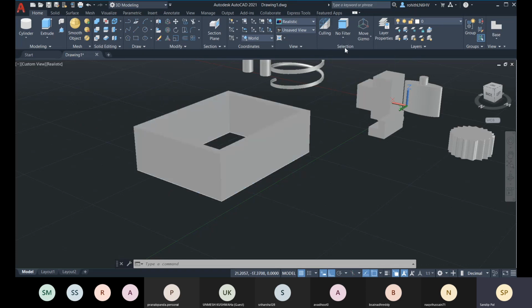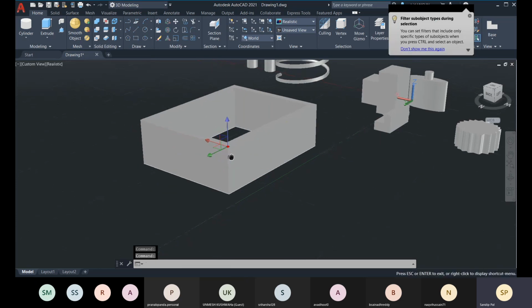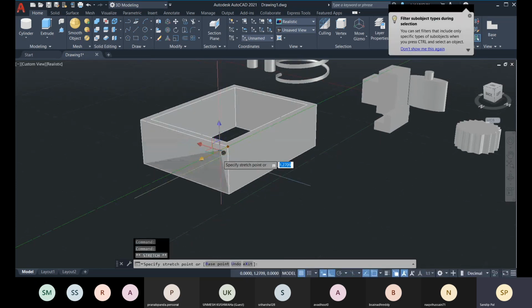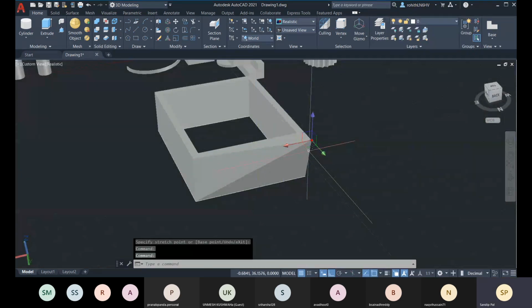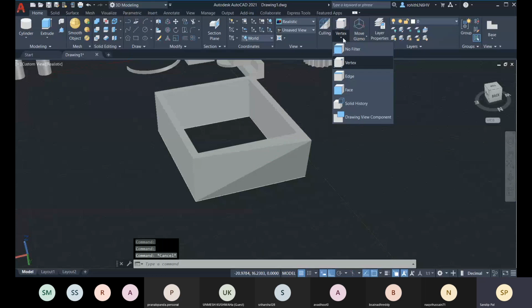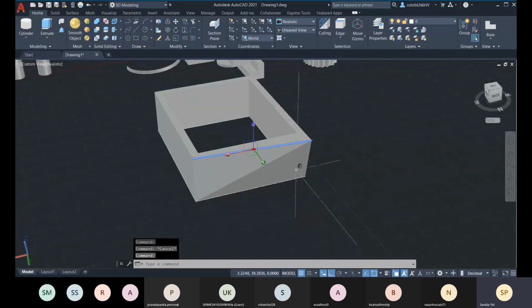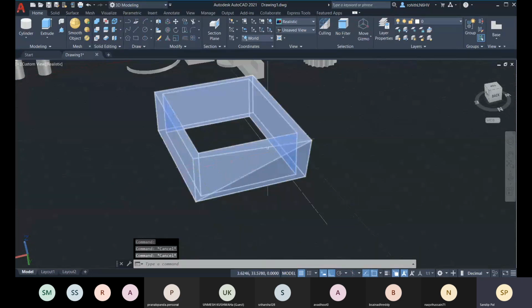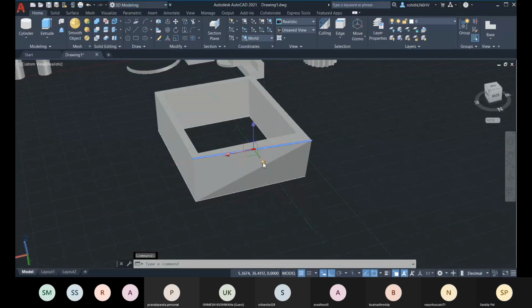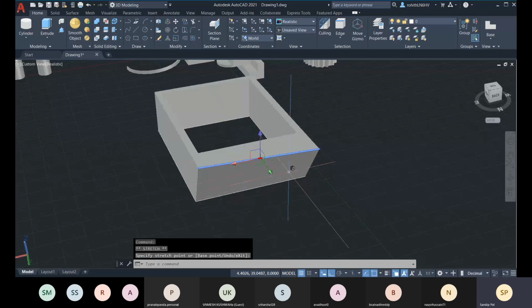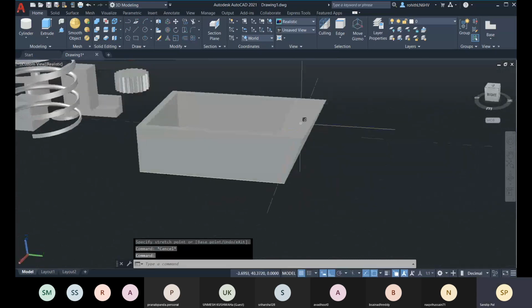What will be selected? What do you want to select? If you choose vertex, right now you can only select the vertices. All the corners are the vertex points. Now if I change the position of this vertex point, I have another form of this 3D element. I can choose edges as well. So this edge option is right now selected, and I can only select edges. Then you can drag it and change the position, and right now you can see.